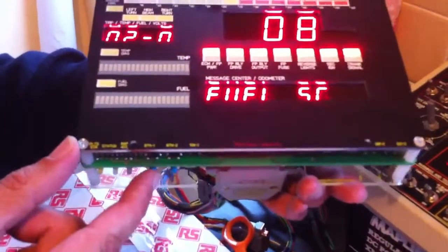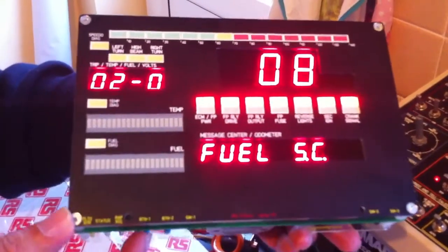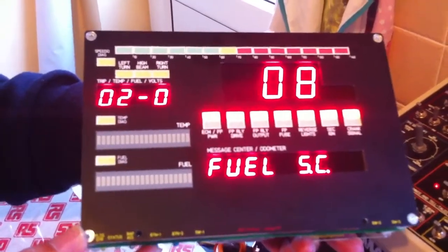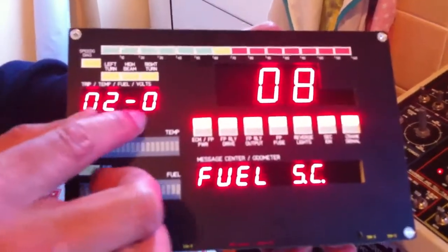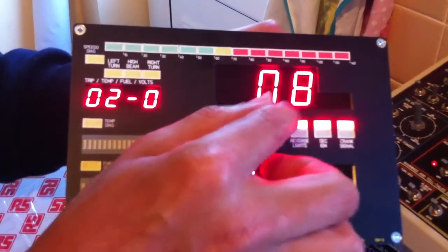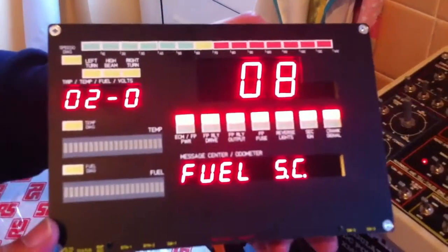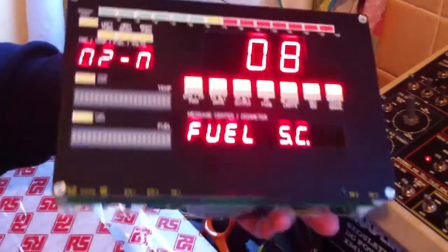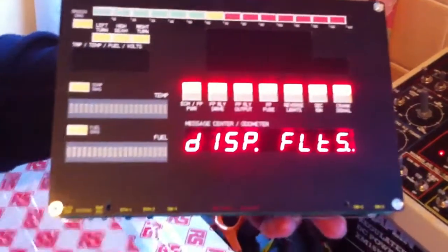If we push button number 1 repeatedly now, it doesn't do anything. The reason for that is button number 1 cycles through all the faults which were stored on the displayed fault word, and because there was only one, 08 is actually a binary value of 0001 000, so that means there's only one bit stored. That's why you don't see anything else. If we push button number 2, we'll see that that's all the faults that are stored.